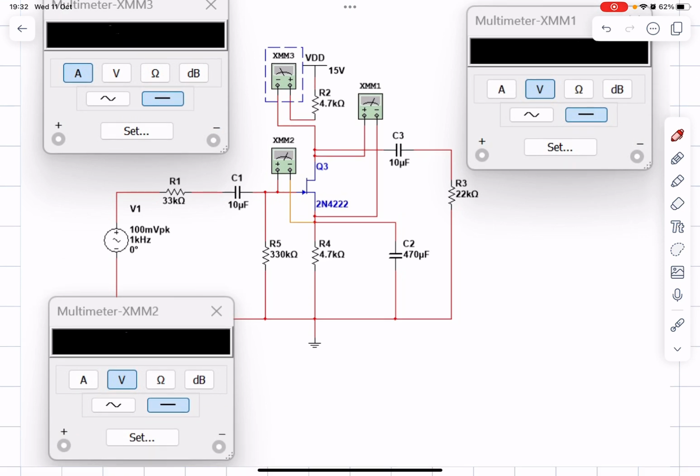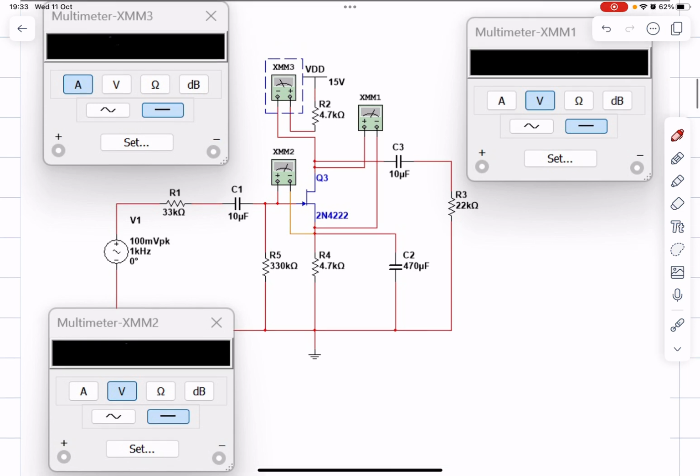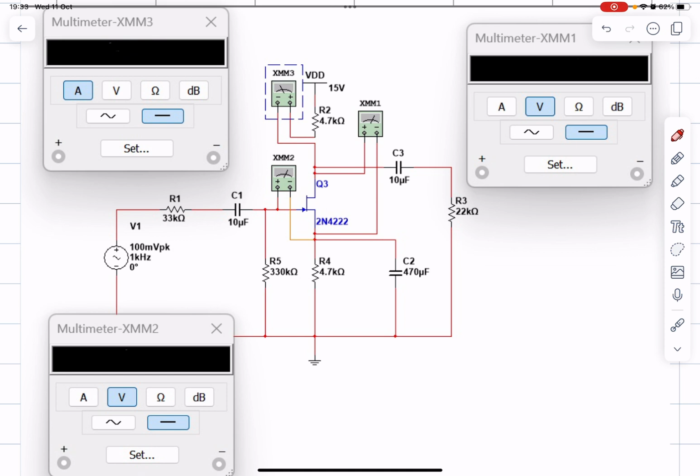This is your example from lab number 9 for FET biasing and amplifier, but the difference between lab 9 and this example is that the source terminal here, I make it into ground. In your lab, it is connected to VSS. So the biasing will be quite different compared to this one.